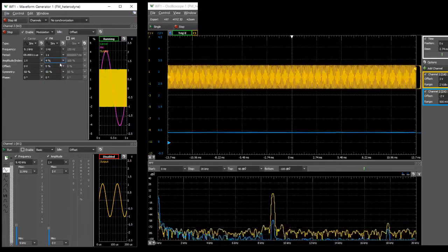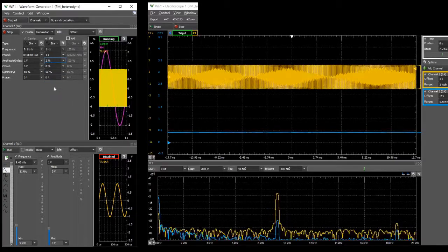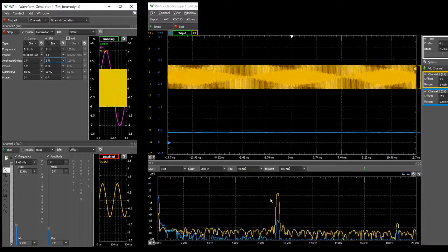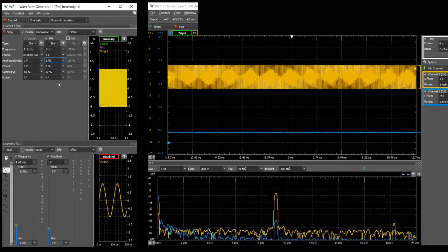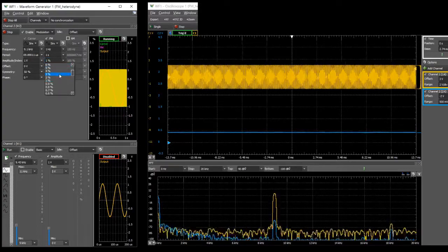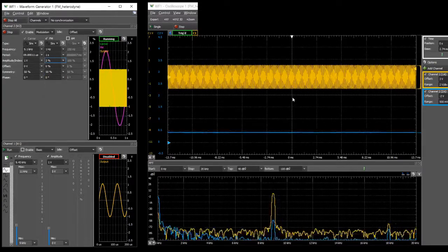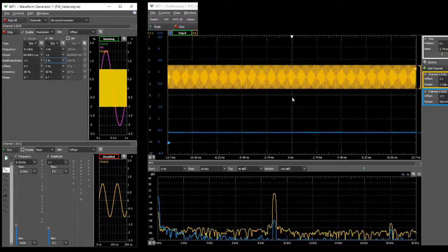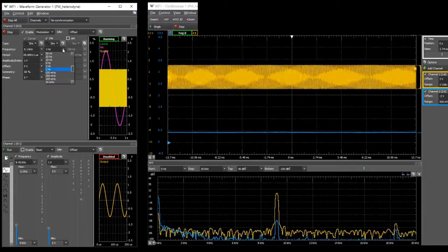How much the frequency changes, or FM amplitude or index, is like how big an airplane is. A large airplane can carry more passengers, but at the cost of more space and higher operational expenditures. Large FM amplitude will make the channel bandwidth larger, which can have a higher data rate. In the frequency space, as discussed in other demonstrations, bandwidth is a prime real estate.